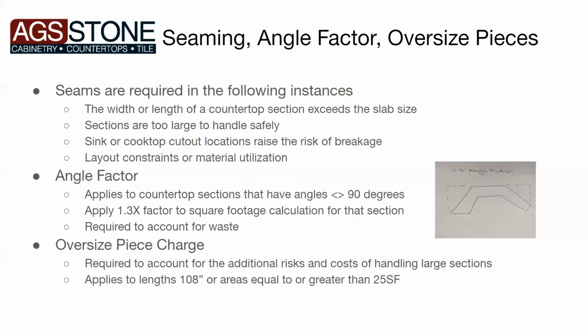But since we want to avoid seams wherever possible, we often end up cutting sections of this. Maybe we still have to seam it somewhere, but we typically don't want to seam it here. Because of that, we end up with a whole section of material here that we can't use. That becomes useless, and we'll call it scrap. It's not large enough to do anything with.